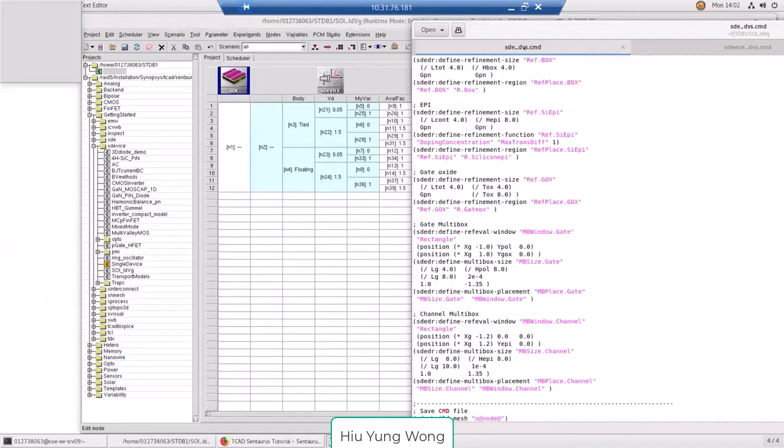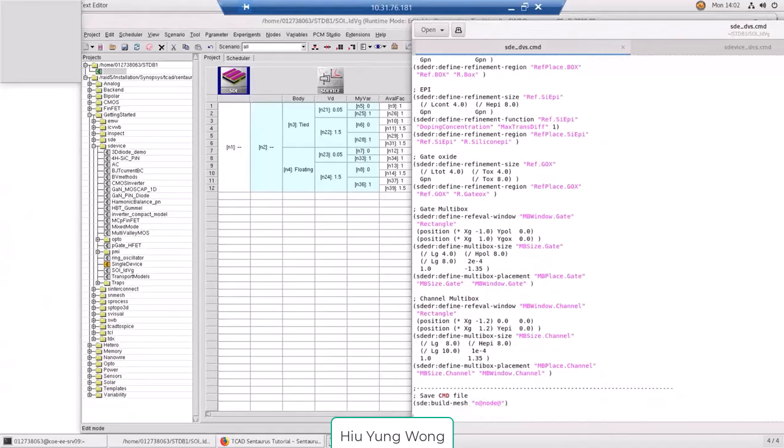I go to SDE. You will see, hey, why do I have something called node, add node, right? I told you that add itself is a variable. So add node add, you may say, would that be a problem? I did not define something called node. So there's something called built-in variable in SWB. Node means that it's going to take the node number. For example, here is 1. It's going to substitute this one by 1.